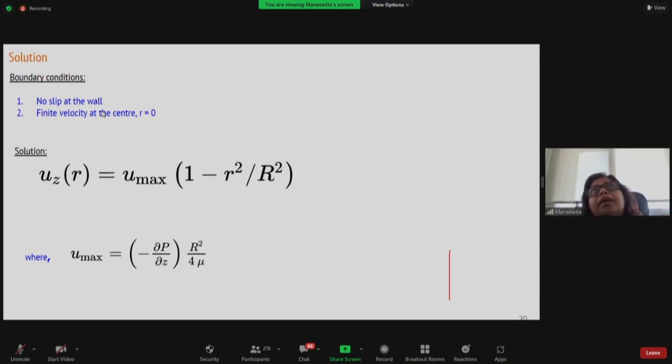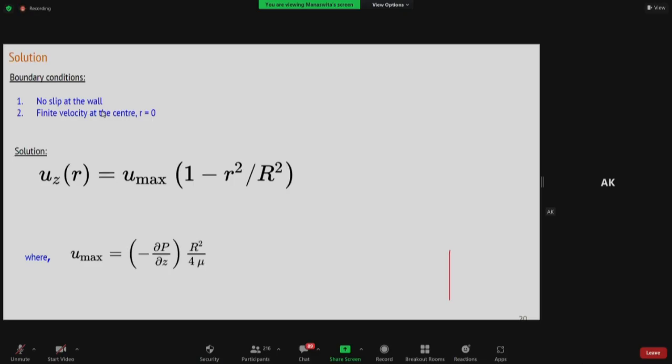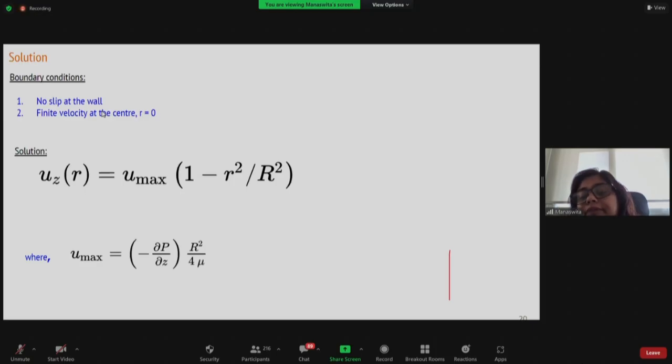If you define pressure inlet and velocity outlet, have the same boundary condition: you have the U inlet and delta U equal to 0 at outlet, and the same thing for pressure also, like P inlet and delta P equal to 0. I think that will be over specified. You can try. I do not know, but I think one of the boundary conditions will be overridden within the code. Just try and see what happens.